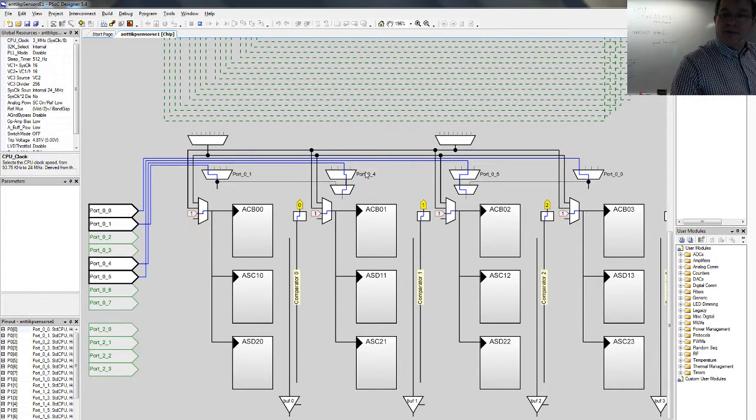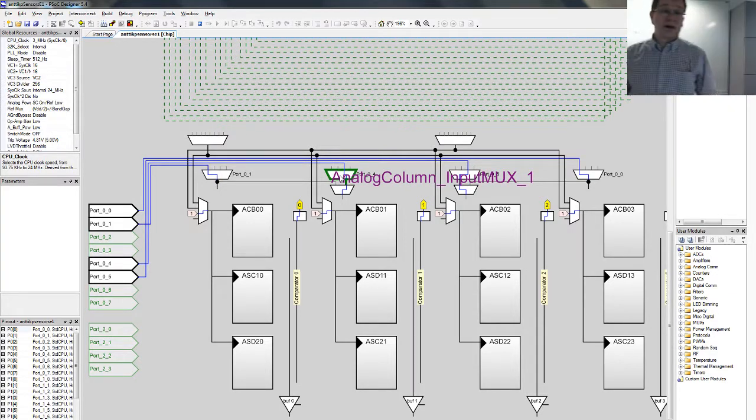But for those analog pins, you have 4 multiplexers. One is for the odd pins, port 01. Actually, it's a 4-bit multiplexer to select any of those odd pins 1, 3, 5, 7. The port 04 multiplexer is actually for the even pins 0, 2, 4, 6.